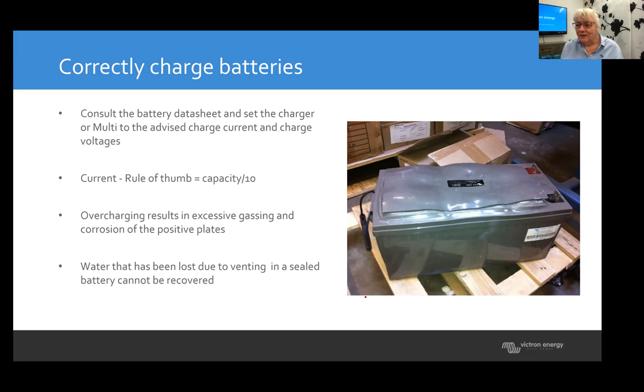That's also a way of telling if you have a good battery or a bad battery. Both might claim to be 220 amp hour batteries. You weigh them and you find 10 kilos difference between brand X and brand Z. Then you know that the heavier the battery, the more capacity. Sometimes people lie or have really small print at the bottom of their data sheet, and then in ideal conditions, all of a sudden it has a lot more capacity.